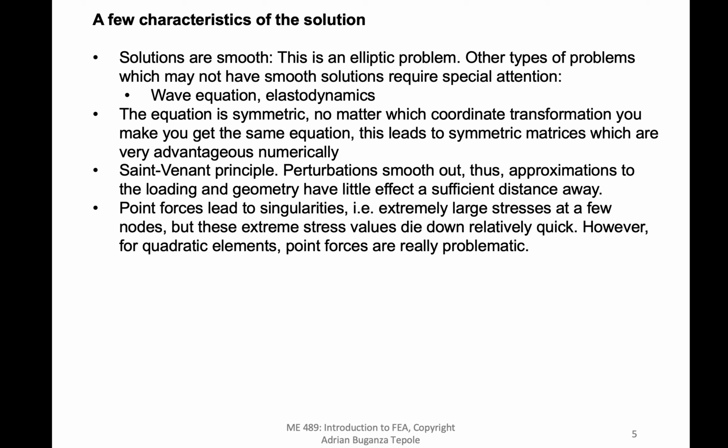So one of the errors that you might have, for example, is that point forces lead to singularities. That is extremely large stresses. And you have probably seen that we did this at some point. For the beam bending example, we applied a shear force, but we applied it as 2 point loads. So we did a simplification there.